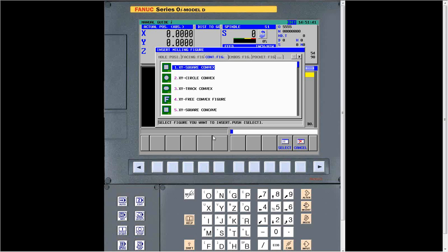So there are a lot of parameters, because usually Manual Guide i will come in configured on a base machine. A lot of times, if you're getting into multitasking machines that are truly 5-axis, it will do 4. You can't do 5 within Manual Guide i. But the 4, for what you're talking about there, would be enough to do the chamfer, because the configuration is standard. So yes, it could do that. We just have to set it up correctly.